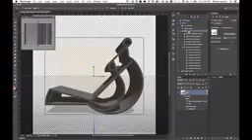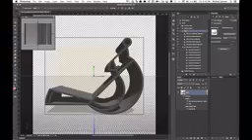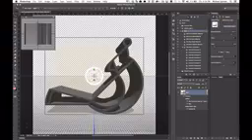Find your way back to the 3D panel and select the 3D object itself. It's the one called Bird. Now the options in the Properties panel have changed as a result of the selection we've just made in the 3D panel. In the Properties panel, click on the second icon. That's the option for Deform. Here we are going to modify the extrusion depth of our model.